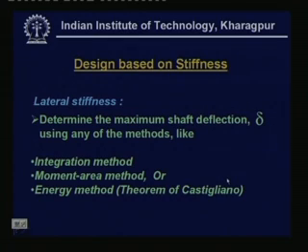Prior to discussing the design based on stiffness, let us make a concluding remark on the design for strength. As far as the design for strength is concerned, you have seen that we have only utilized the basic stress equations we learned in the earlier lectures, and those strength theories. One was the ASME design code, another was the design for fatigue, for which we used the Soderberg criteria.